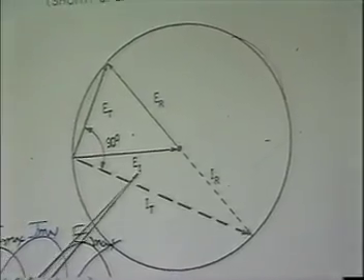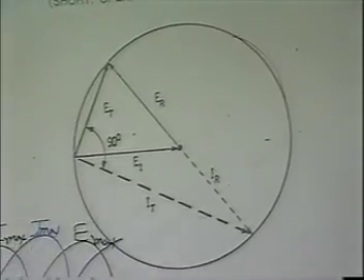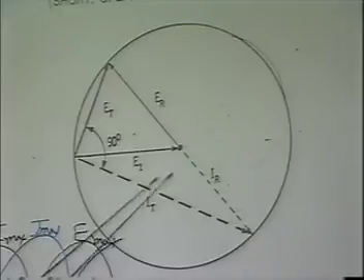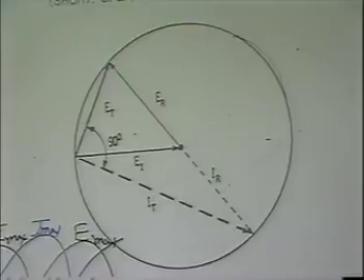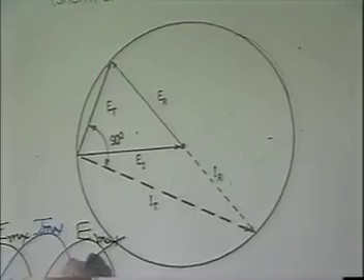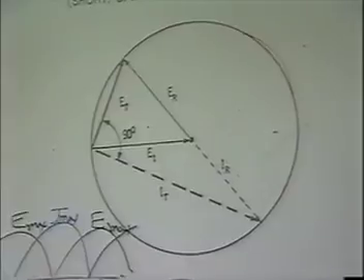The total current then is over here, this point here, and you can see the angle between the voltage and current is 90 degrees. Well, there's one thing we didn't talk about before. Why is the current vector shown as being over here? On the transmission line, the current and the voltage are how far apart? 90 degrees apart. In this case, they're 90 degrees at all times.